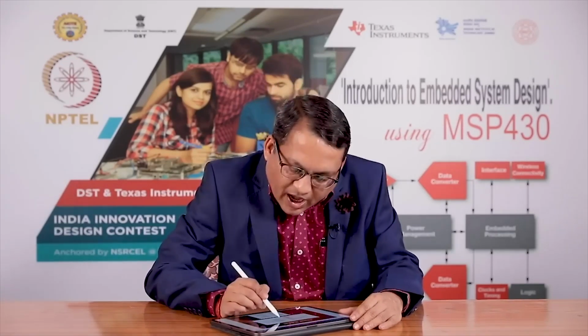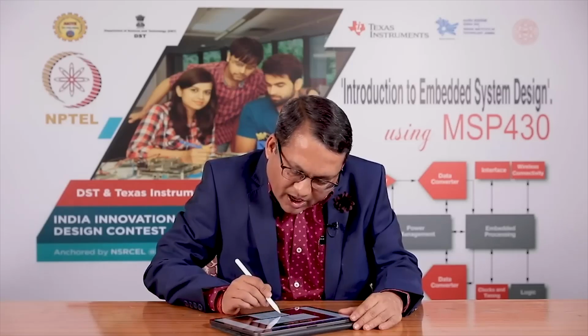And these pins which are designated as RST bar or RESET on these two microcontrollers refer to the user reset, meaning user can assert a logic level on these pins and it would reset the system even if the power supply was not taken off, even if the power supply was applied.